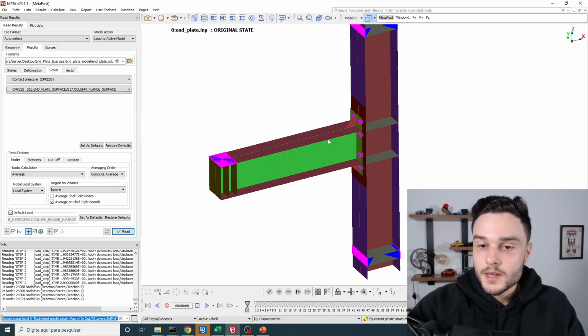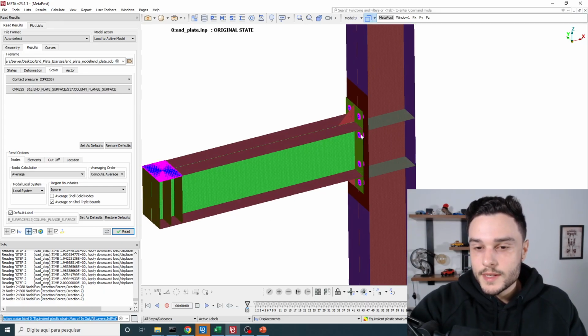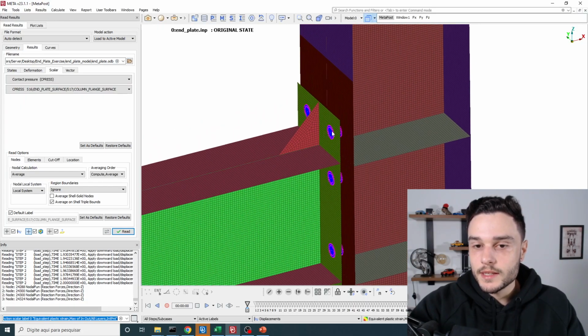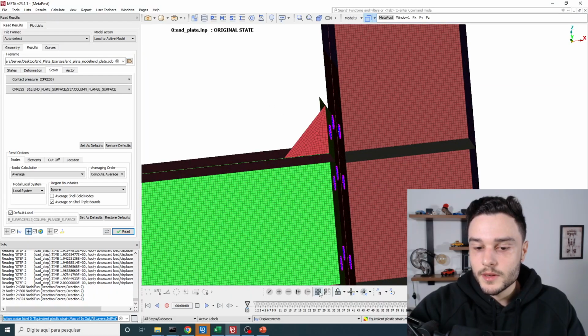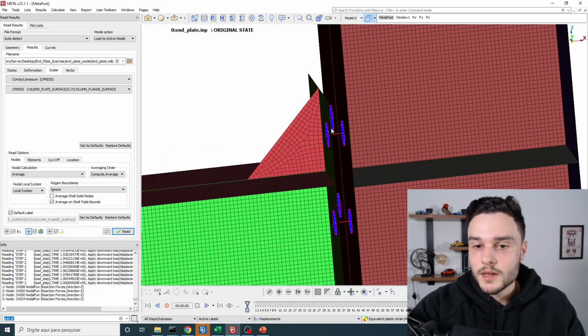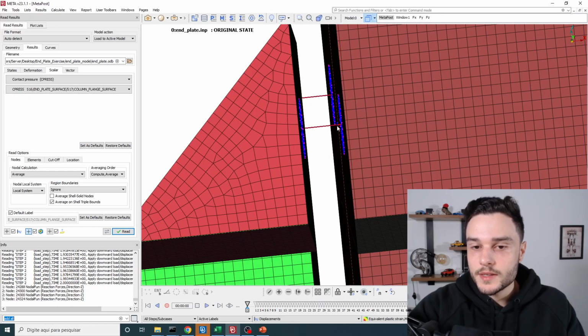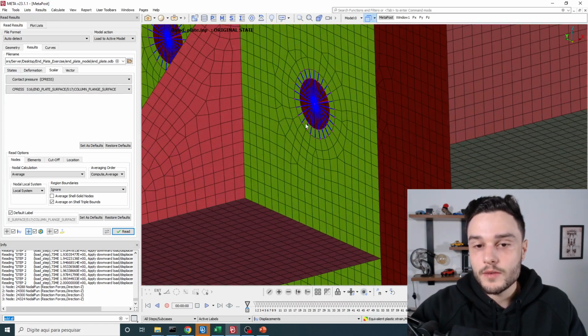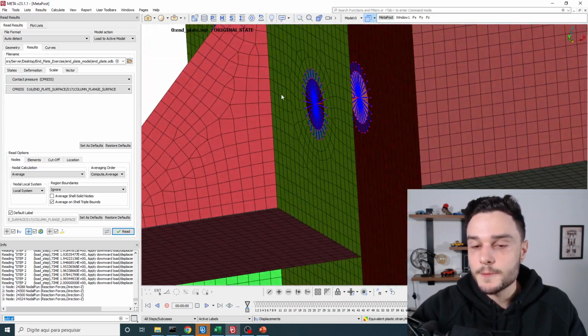Okay, so let's start analyzing the beam. We didn't analyze the beams yet, right? Let me click and show all. You see that I have the beams here, right? I wanted to see how the translator connector applies the bolt pretension in the beams, because we have used a translator connector, right?